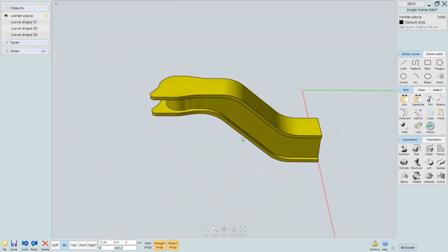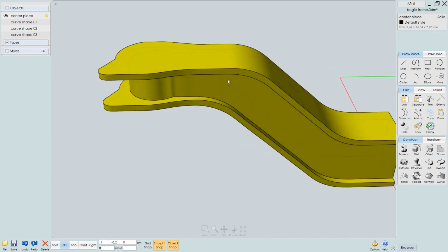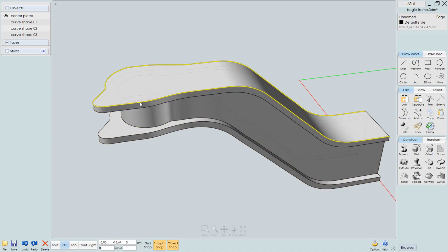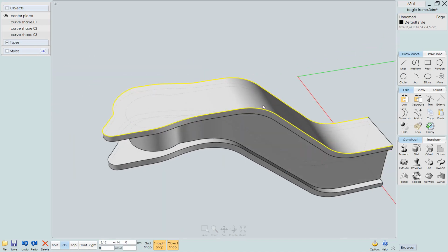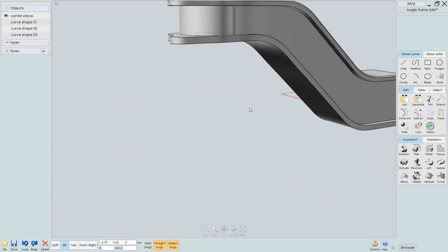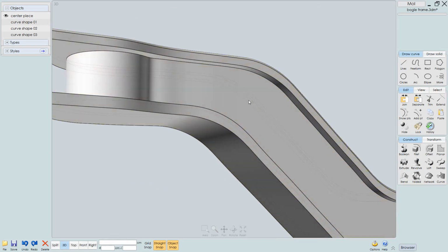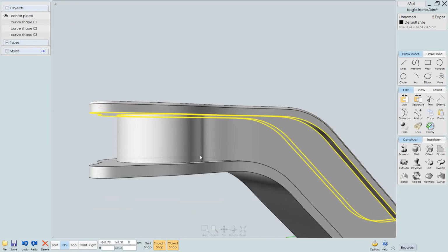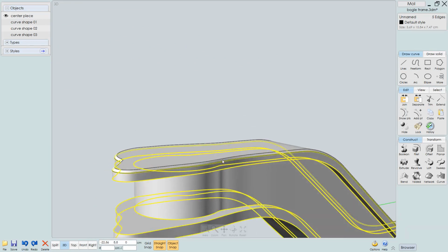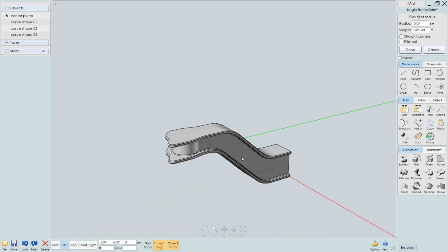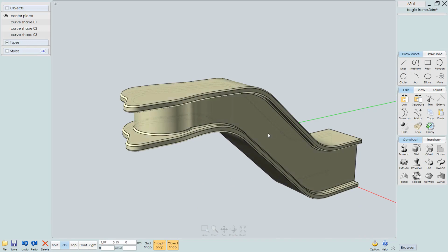So I'll just hit escape and fillet the edges separately. Let's select the object, select this edge, and because we don't have any other edges, you should be able with just one mouse click to select the entire loop here. So let's fillet this with a radius of 0.7, confirm, and then we're just going to go around this object, and actually we can select all of these curves at once. We don't need to do these separately. So let's select all of these edges and do that fillet. That's looking good. So I'll right click to confirm that.